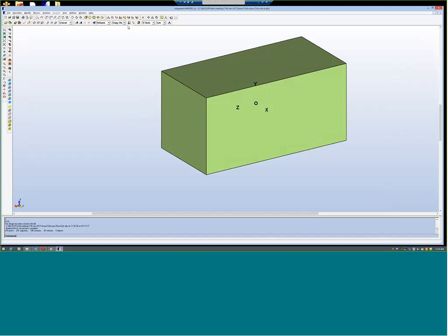On the surfaces, on the material interfaces, for example this top surface, it is a material interface between 2 materials. Below that highlighted surface, it has 1010 steel. Above, it has air. So that surface is a material interface. You have to put 2-dimensional mesh on that.